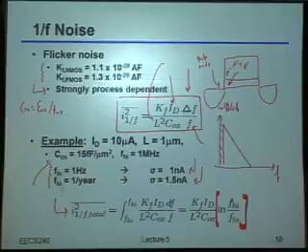Maybe just from a purely mathematical standpoint, because I have this logarithmic behavior, you can really reduce this low frequency limit over which you're trying to operate the circuit quite a bit and still not have a huge impact on the net variance of the noise that you'll see. Okay? Does this make sense to everybody? Or again, this is a fairly popular point of confusion, so if you have questions, please do speak up now.